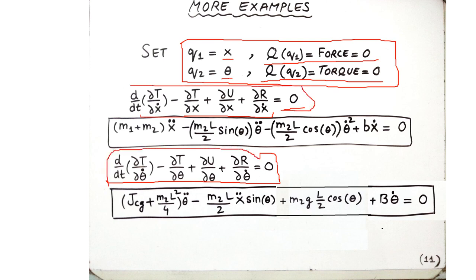The components of the left hand sides have been pre-computed. You can just plug those in and obtain the final expression obtained from the Lagrange equation of motion. Remember, there is a potential energy term involved in the system associated with the potential energy of the pendulum bar. So this term is basically partial u taken with respect to partial theta. That must be included.